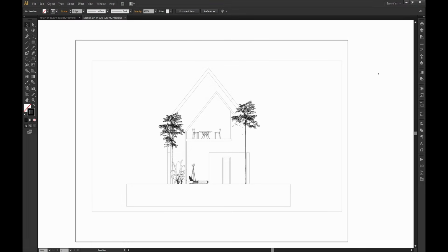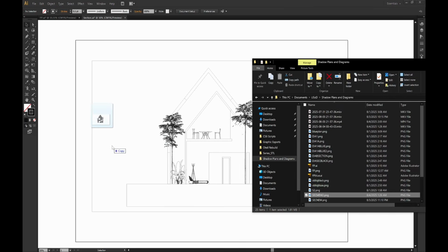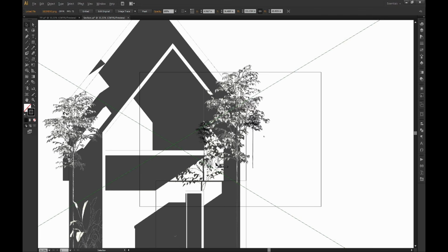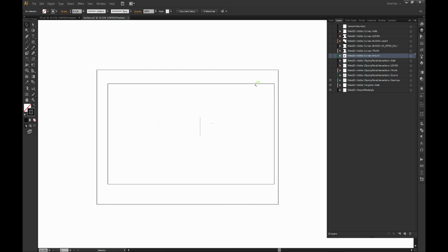Okay, so here we are in Illustrator, and I'm just going to go through the exact same process like I did for the previous floor plan in that simpler, smaller section. I just want to reiterate the process so you understand the workflow. So the first thing I'm going to do is put in that screenshot. I can just drag it in here like this. And if you remember, the viewport of this screen capture is the same size as the viewport of the Make 2D, so I can just match the sizes of both of them.